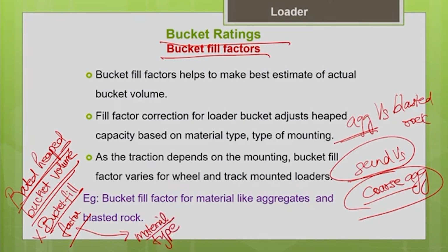So, this value also I can get from the literature. For different materials, depending upon the size of the material, the filling ability will vary. So, the bucket fill factor will also vary. It not only depends upon the material type, it also depends upon the mounting of your machine. Your machine may be either wheel mounted or track mounted.